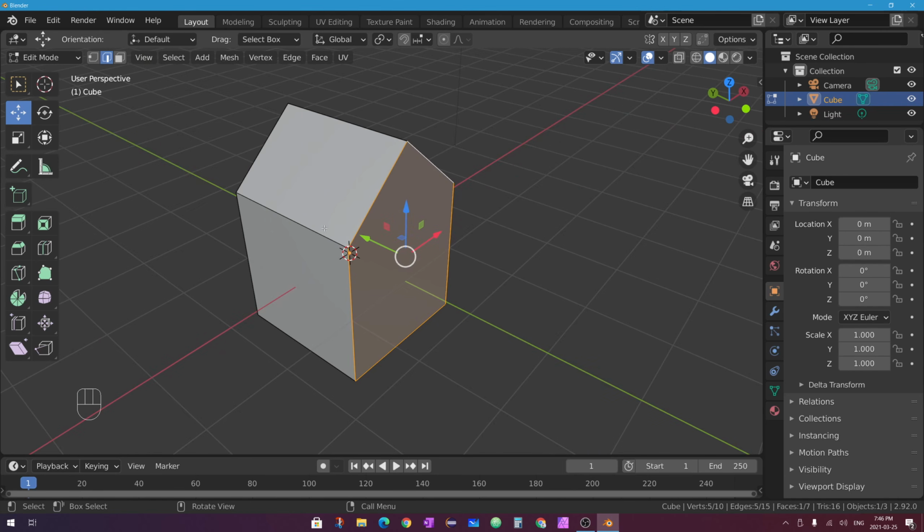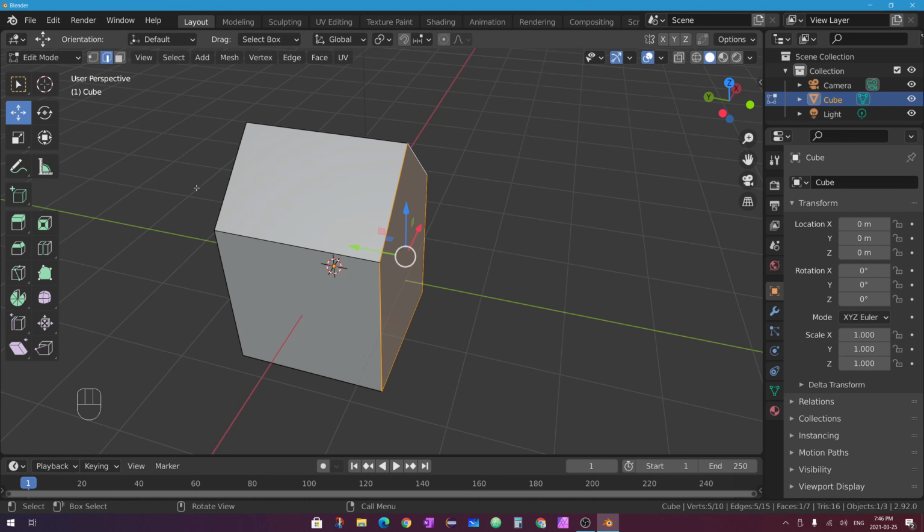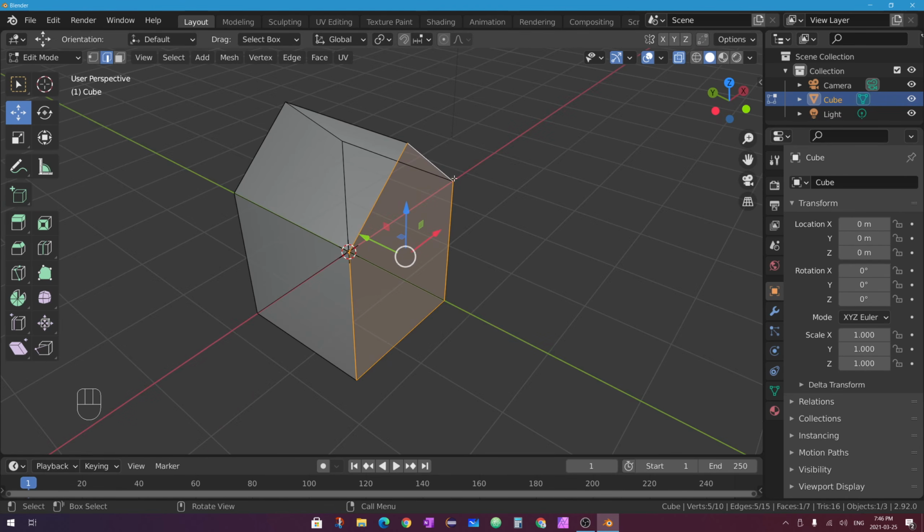The topology of a mesh is the organization and flow of edges and faces and surfaces along the shape or around the shape of your 3D object. N-Gons can be divided up into quads or tris. Typically, quads are ideal, especially if you want the edges of your mesh to run nicely. I'll turn on X-ray mode, nicely around your mesh in loops of edges called edge loops. So keep in mind that N-Gons, what we have now, is not totally ideal.